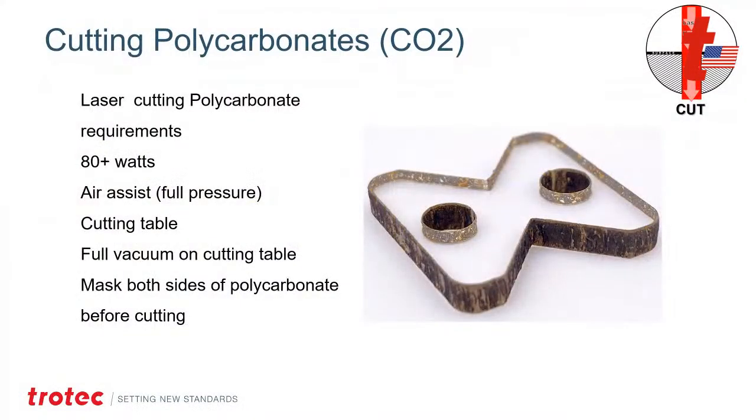Now, cutting it is very doable, but the edge quality can be rough looking. And this is due to the carbon in the material. When the laser hits it, the heat reacts with that carbon, and we tend to get this crunchy, black, sooty residue that forms. It can be rubbed off with a pumice or even a small amount of sandpaper.